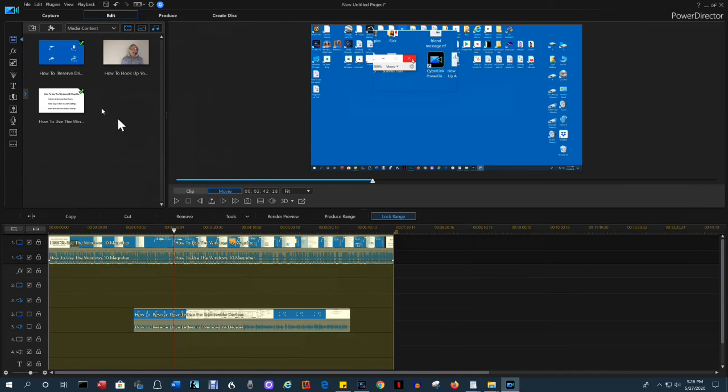It will put the produced video here and in the project file. And again, check it over. If you've produced it with produce range, make sure it's correct. If it isn't, come back in here, delete it from the media library and from the project file, and then edit it some more and then produce it again. With produce range, it'll start and stop where the range is.